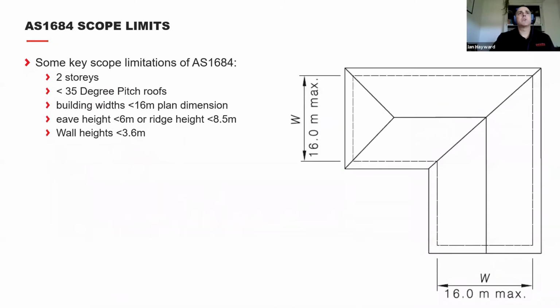Okay, so if we look at the scope limits of AS 1684, we need to stay within these parameters to get the deemed to comply provisions to be working for us. Outside of these provisions, it needs to move to an engineered solution.